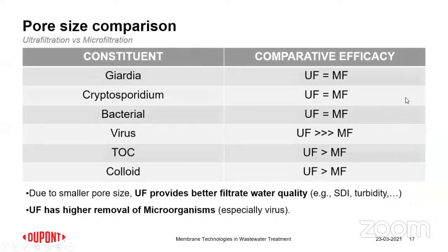So besides this, there are many reasons that a UF-based filtration is used, simply because of the point that we were speaking about, consistency in the filtrate quality, and also ensuring that all biology, including virus, is removed. Of late, this is the most important thing that one must ensure is being removed. For this reason, at least, UF is a better technology.